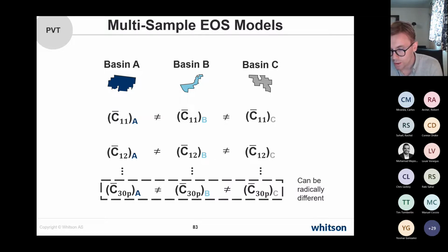Those components are well known. We can find their properties, molecular weights, etc., in any chemistry textbook. But if we take C15, for instance, if you measure that in the lab, a C15 is not a C15, because C15 can be made up of 1,800 different isomers. And what you're measuring is essentially just some kind of field average of C15.